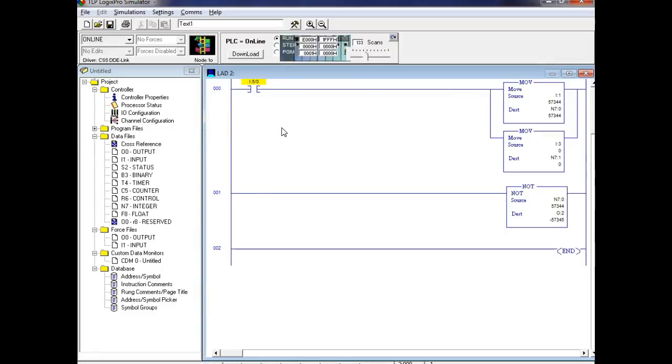And you see some of these, there's a lot of PLC stuff, especially these little small PLCs that don't cost that much money. Used to you'd have these signs on the side of the road and it might have a big arrow up on top of it, and it looks like the lights are going in sequence, like it's pointing. A lot of times on marquees, you'll have the lights blink alternate from each other. We'll show y'all the bit shift is what we can use to implement the lights that appear to be in motion. This guy right here, we could do this to make the lights blink.